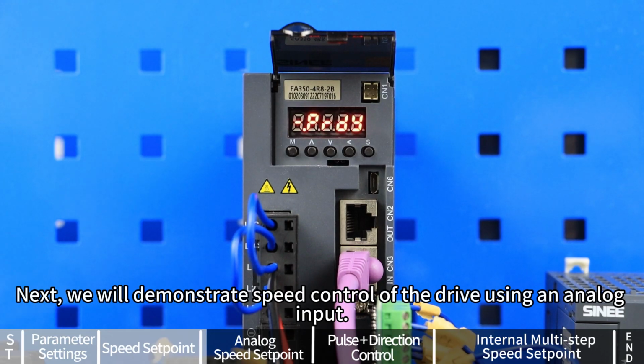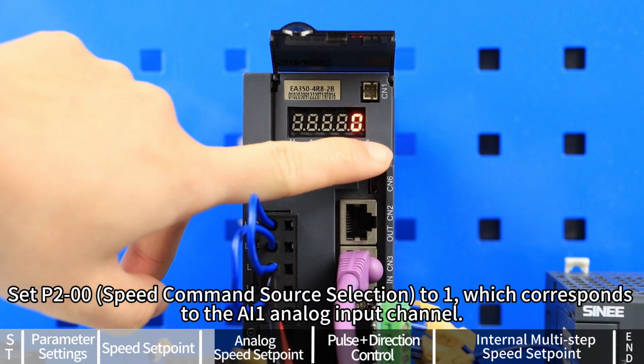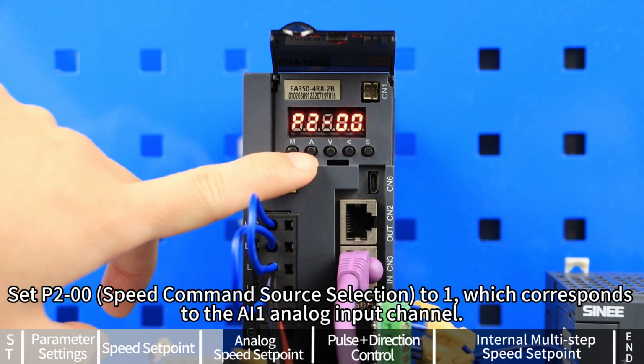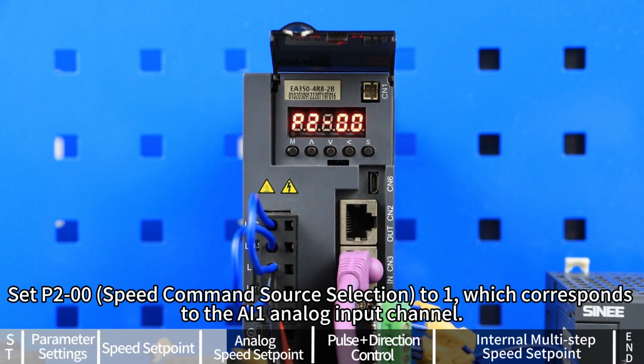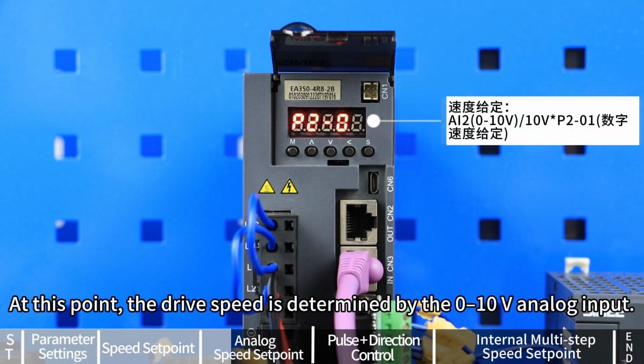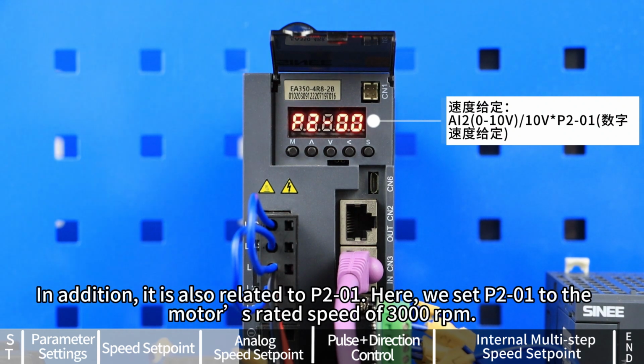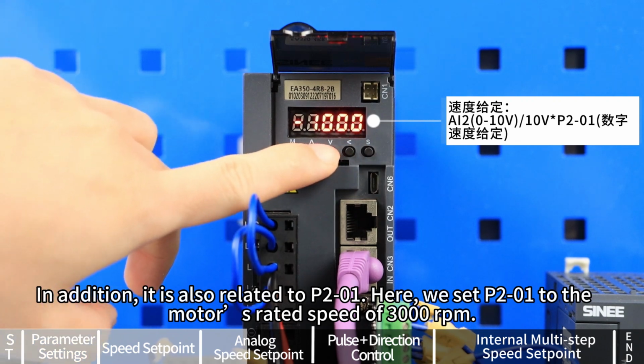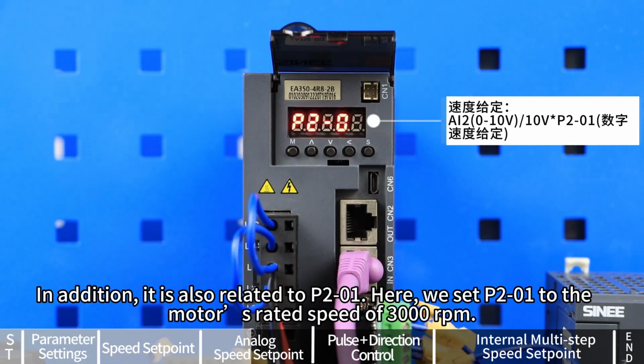Next, we will demonstrate speed control of the drive using an analog input. Set P200, speed command source selection, to 1, which corresponds to the AI1 analog input channel. At this point, the drive speed is determined by the 0 to 10V analog input. In addition, it is also related to P201. Here, we set P201 to the motor's rated speed of 3000 revolutions per minute.